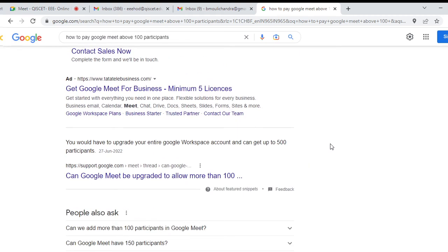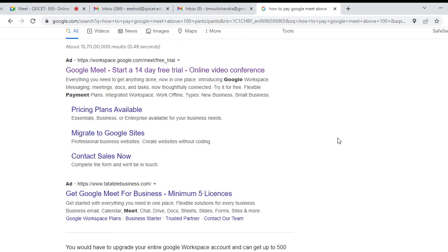We have a total of 8 buses. Out of those 8 buses, bus number 1 and 2 have some kind of source. That's why we have not calculated their stability value. Bus number 1 and 2 have generators, so we have not calculated their stability value. But the other buses have loads, and for these loads we have calculated the stability value. If the value of the stability index is near 1, it indicates the system becomes unstable.